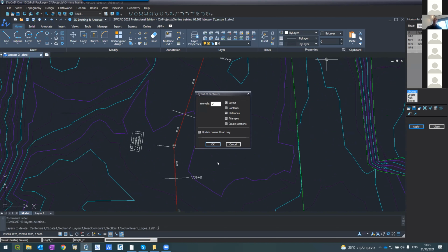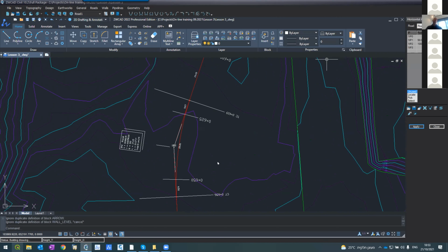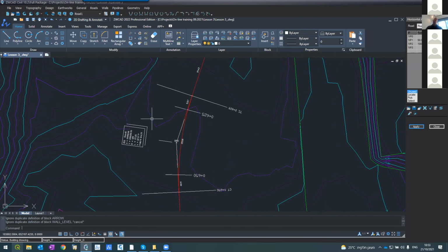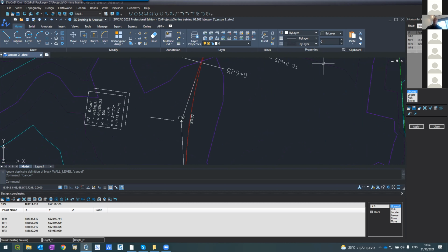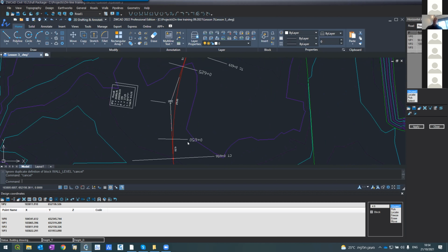Yes, someone asked me a question, let's see. Okay, what I did right now, I repeated it again. I created another curve. How do I do it? In the road's horizontal alignment, I have the road. I'm going to the relevant IP, the IP which sits opposite here. This is IP2. You see it here. And I enter the radius. In this case, I enter radius 100 and apply.